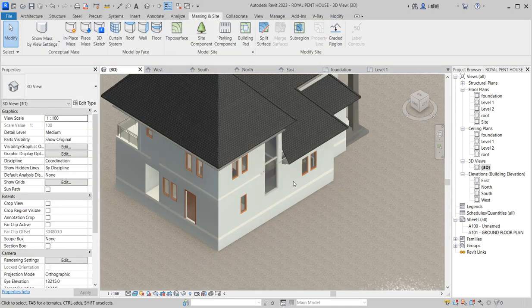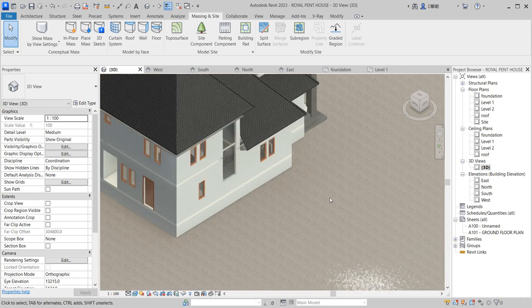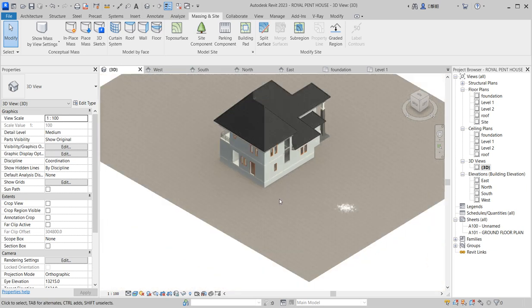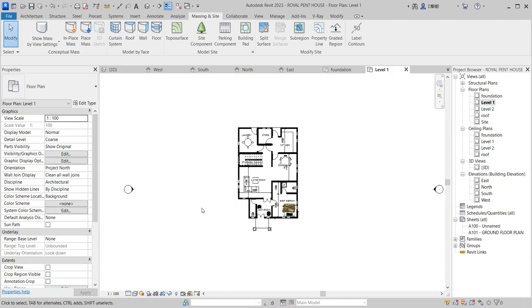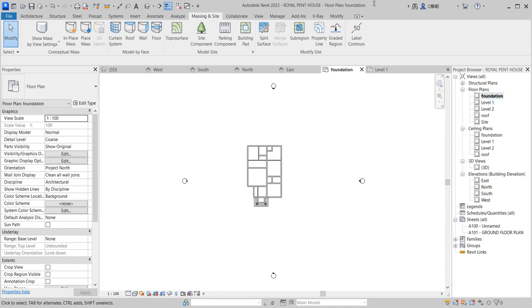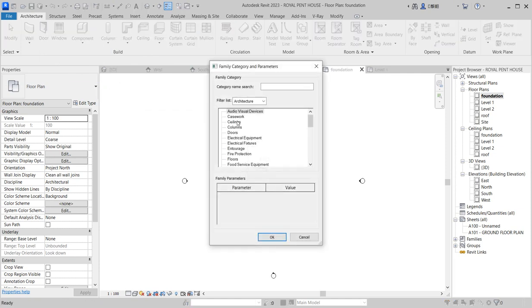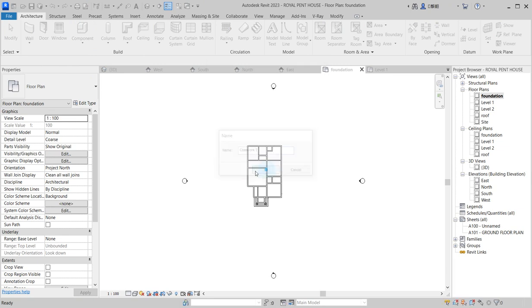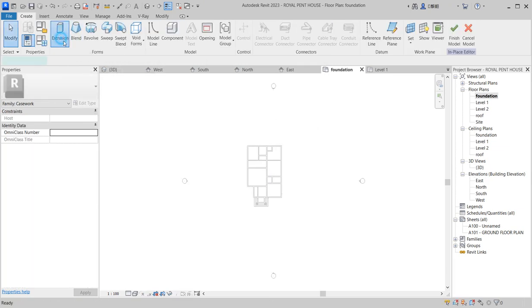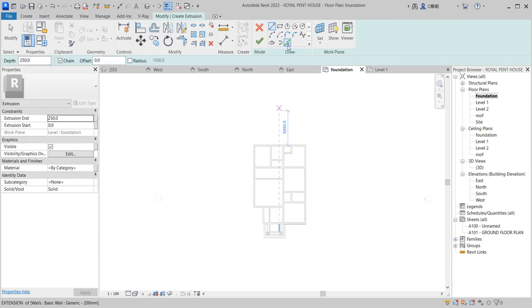So that is the beginning of what I'm designing in this particular area. So the next thing we do is to go back here. So go to foundation again. So first I want to create around this place the flower spaces. So model in place. So click on casework. On this casework, then you click on this. So you click the extrusion around these particular points